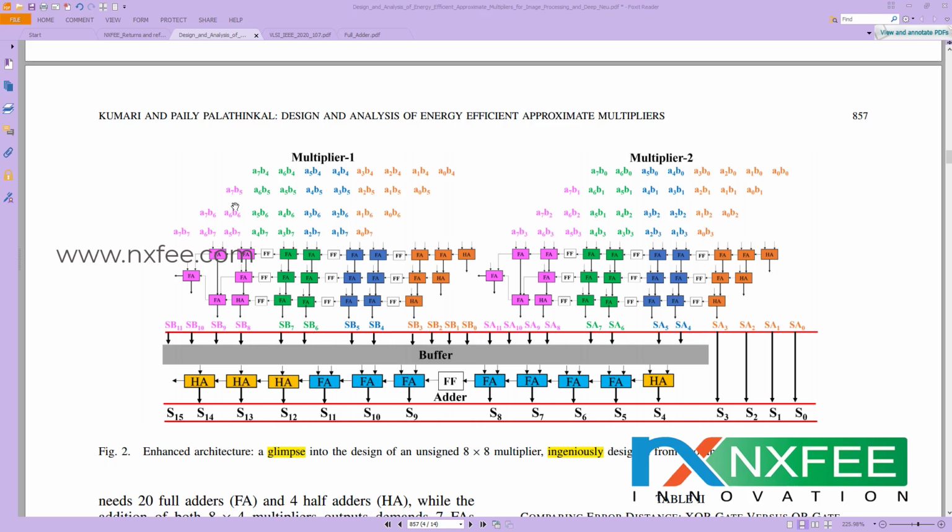After that, the split partial products are reduced using a number of adder tree architectures. That is what these color variations show. Here this is adder 1, adder 2 and adder 3. The same method is handled on the MSB multiplications. After that we reduce to the final output, and we take it as the final partial product output. So this is the recursive method.